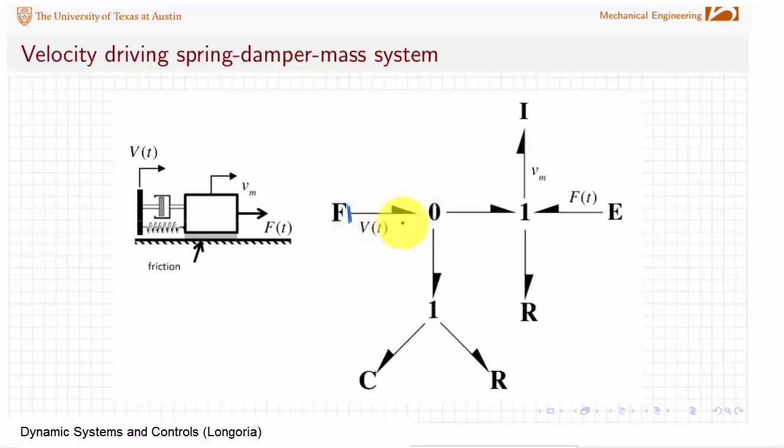Again, you have specified a flow into a 0, so you're not constrained on applying causality on any of these other bonds. So that means we can then move to another part of the bond graph and look for other sources, and in this case we have to apply causality to this effort source because it is restricted, so we apply the effort causality into that one junction. Again, effort into a one junction, where we have not constrained ourselves, we still have freedom to apply causality anywhere else, right? So now we would look for any other sources. We'd see if that causality propagated. It doesn't at a one junction.